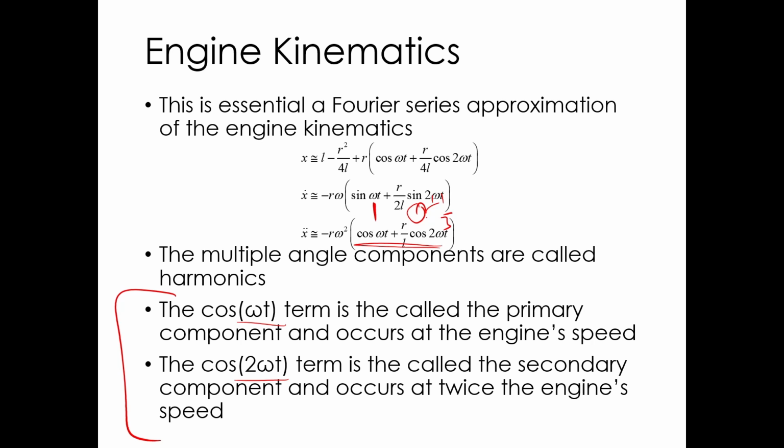And for that you really need something spinning at twice the speed of the crank, and there's nothing in an engine spinning at twice the speed of the crank. The camshafts spin at half the speed of the crank for a 4-stroke. There's nothing spinning twice as fast. So either live with it, which in race car engines and lighter engines you might, or you put a shaft that spins at twice the engine speed. That's a balance shaft. That's why you need a balance shaft for some engines: if you have a secondary balance problem, you need a shaft that spins twice as fast as the crank. And the only way you can do that is literally gear a shaft or put chains on a shaft to have it spin twice as fast and put some eccentric weights on it.